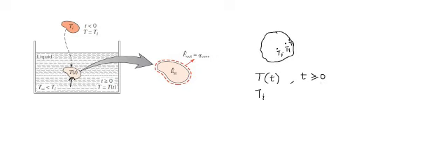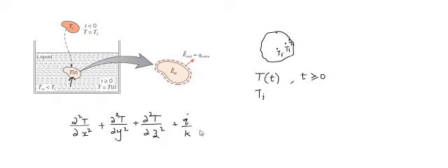One very important thing that we have to consider here is the energy equation, or the heat equation. The three-dimensional heat equation is d squared T over dx squared plus d squared T over dy squared plus d squared T over dz squared plus, if you are considering the heat generation term, q dot over k, equal to 1 by alpha dT over dt.